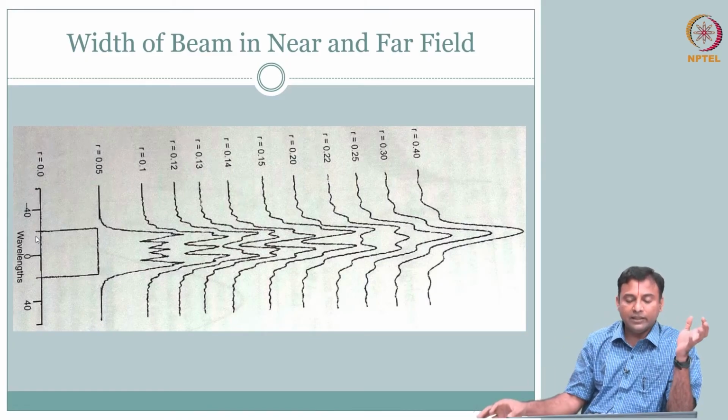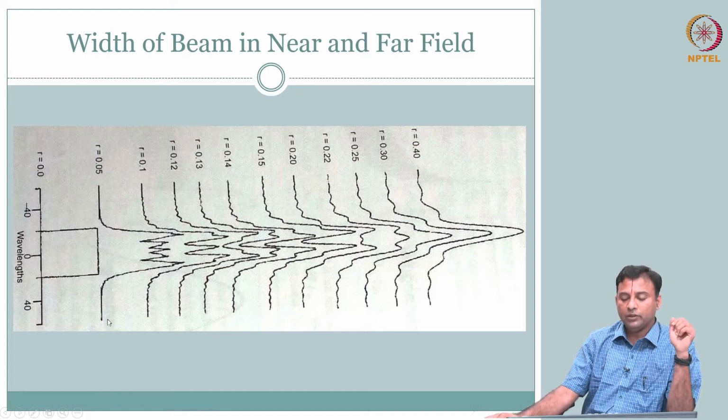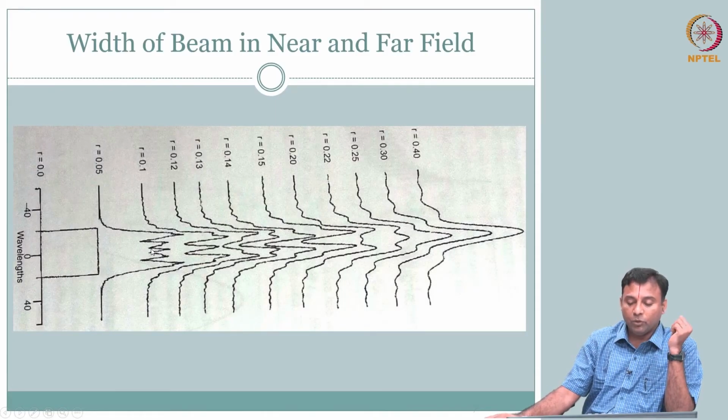A similar thing is applicable here as well. If I have a transducer where only the crystal is here and it is cut such that there is nothing outside, it is a hard boundary. If you have a hard boundary, you are going to have a lot more ripples. How do I smooth it? Window it, shape it. So we will talk about that.